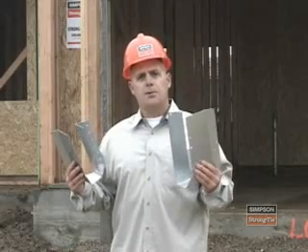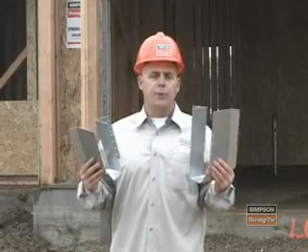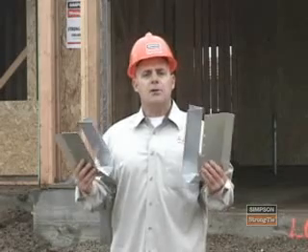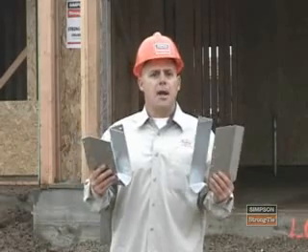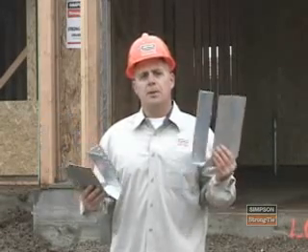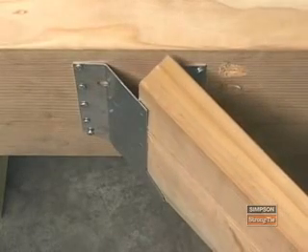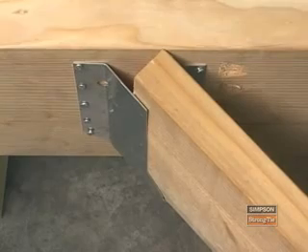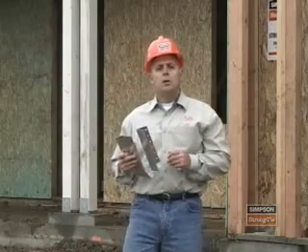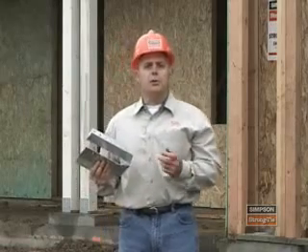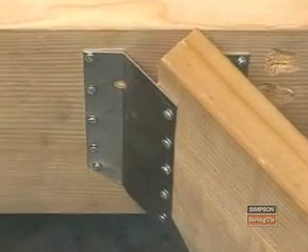SUR and SUL hangers are designed for joists that need to be skewed at a 45-degree angle. These hangers are identical, except that the SUR hanger is skewed to the right and the SUL is skewed to the left. The skew angle is preset, and the joist does not need to be bevel cut for the skew angle. To install, follow the same procedure used with face mount hangers. Here is a correctly installed SUR hanger.